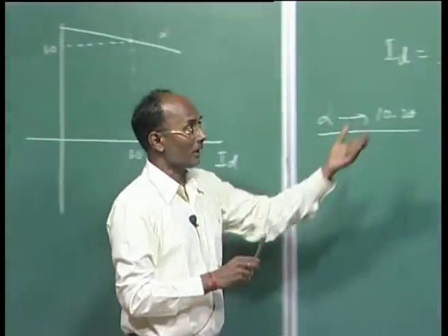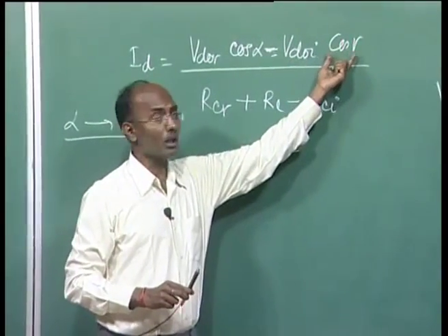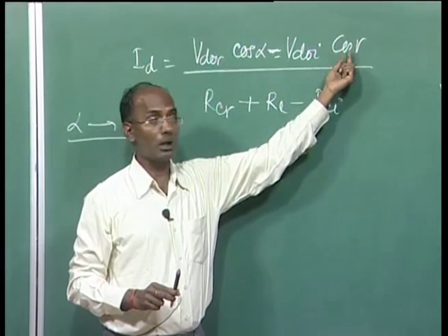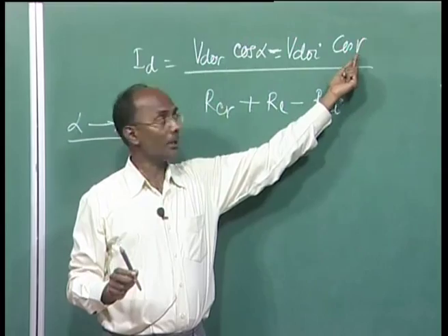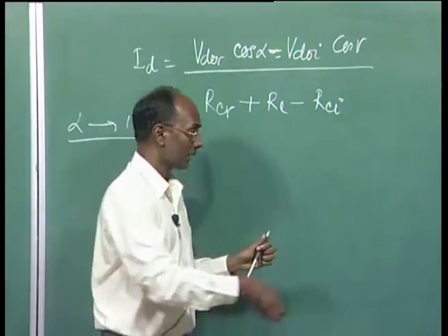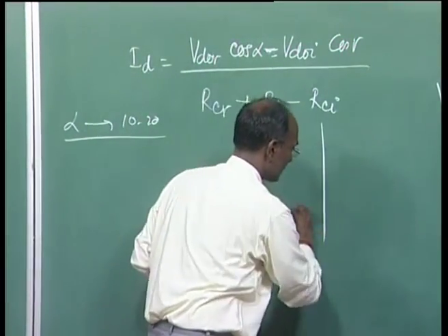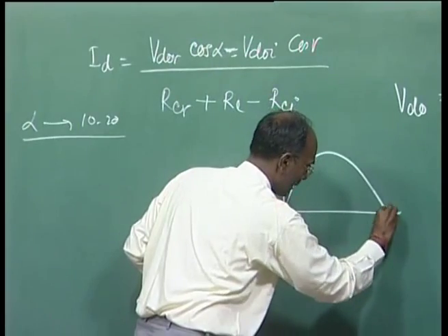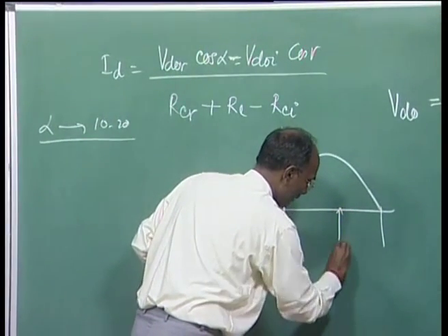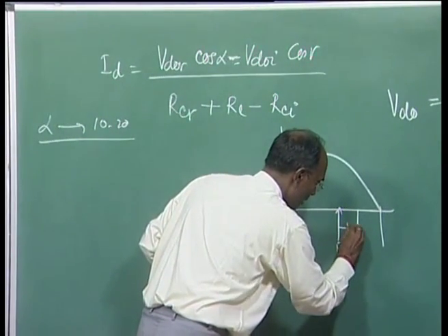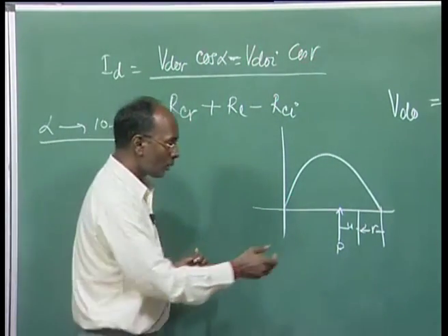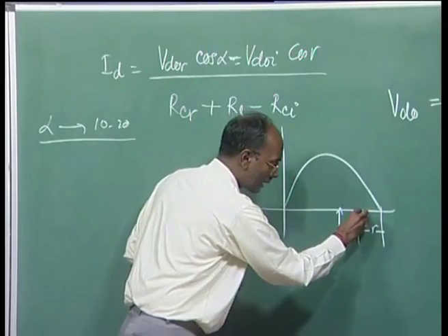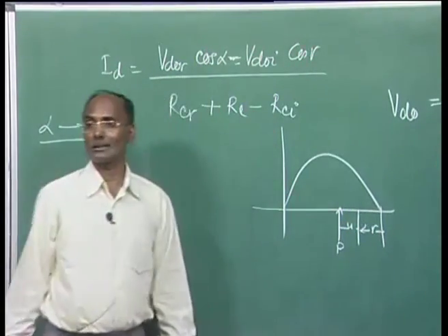we'll see this side we have no control, because we are trying to operate this gamma at a minimum. For example, this is your gamma. Here, from your beta, this is 5, this is your U, and this is your gamma. You can go only up to a minimum gamma value, so that your commutation is successful.